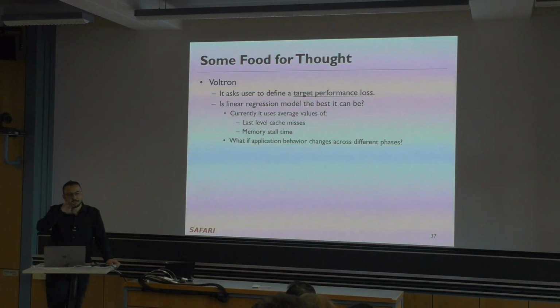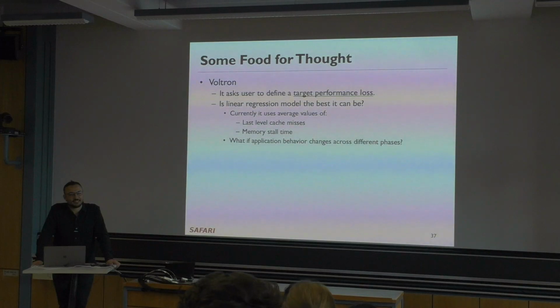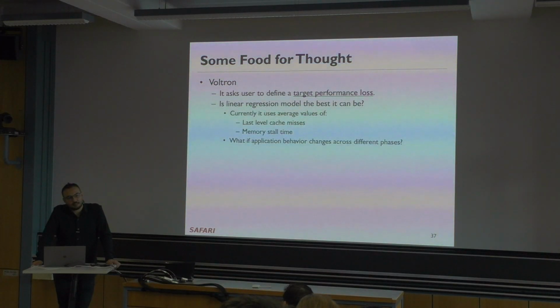So I'm lost in the last part, the register part. First, the activity is something. The power consumption will grow with the activity linearly because it's directly proportional to the activity, but with voltage it will grow quadratically because it depends on the voltage square.